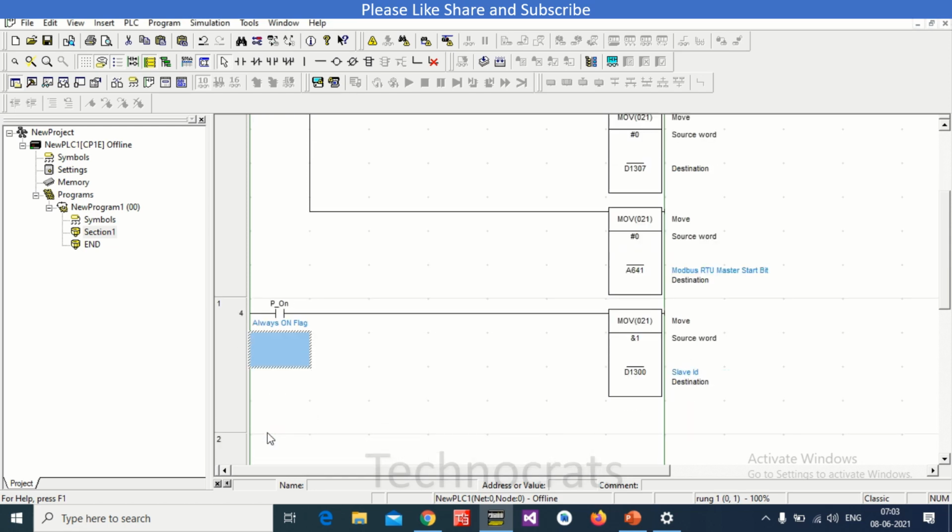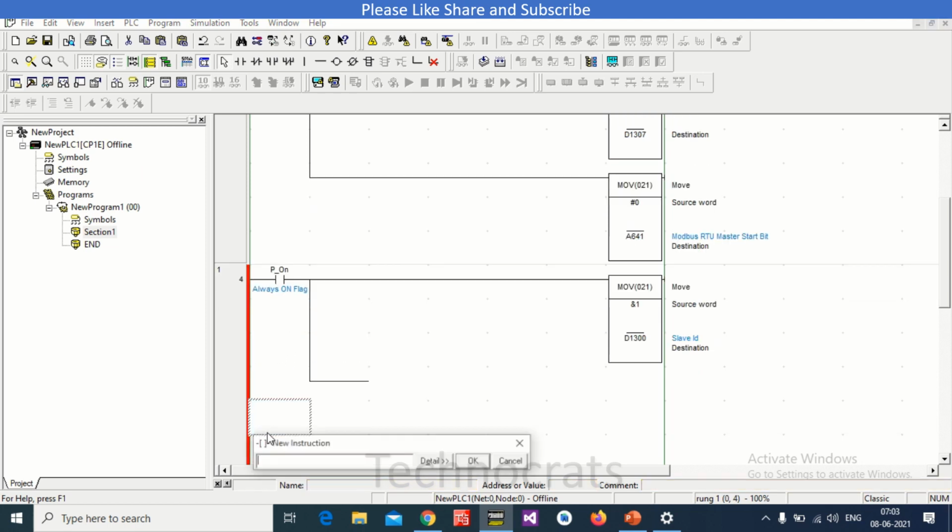So I will use it for slave ID. Now the next one is your function code. So for function code, MOV, and the function code we can put as #10 to D1302. This is your function code.